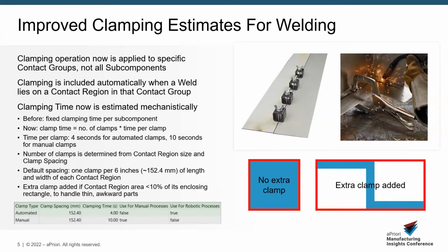Now, this assumption was arguably sound for welding, as most often we see the weldment modeled in its own level within the CAD assembly, in which case it's likely that everything would be clamped. But it's likely not as strong an assumption for bonding. We do see a lot of assemblies of a few dozen parts where maybe only a couple of them are bonded.